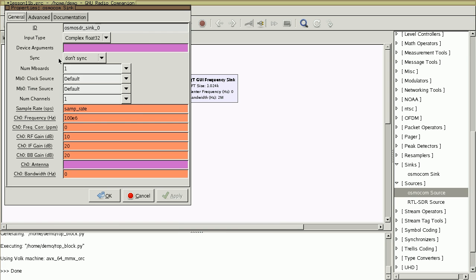Let me take a look and see here. This should be 27 megahertz because that's the same frequency that I used to capture. Now remember that the signal of interest is actually at approximately 27.15 megahertz. But it's a little bit above, it's 150 kilohertz above that center frequency of 27 megahertz in our capture file. If I want to replay it and have it remain 150 kilohertz above 27 megahertz, then I need to have my center frequency exactly the same for my replay as it was in my original capture.